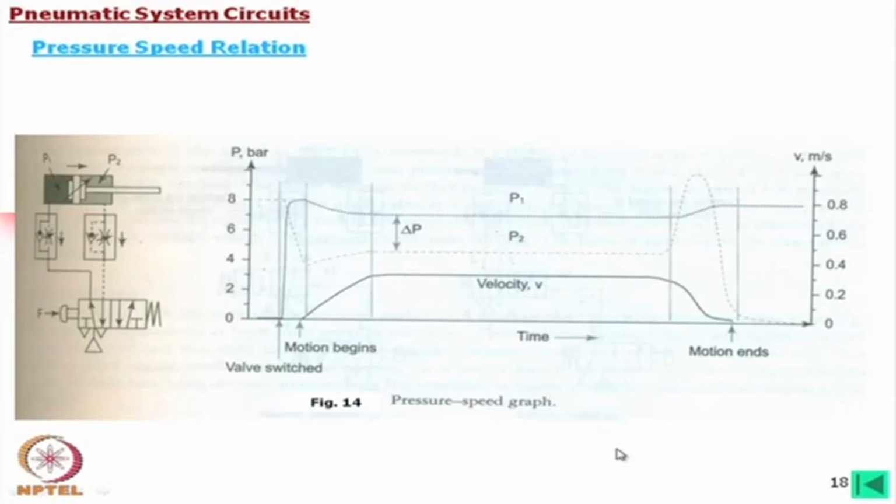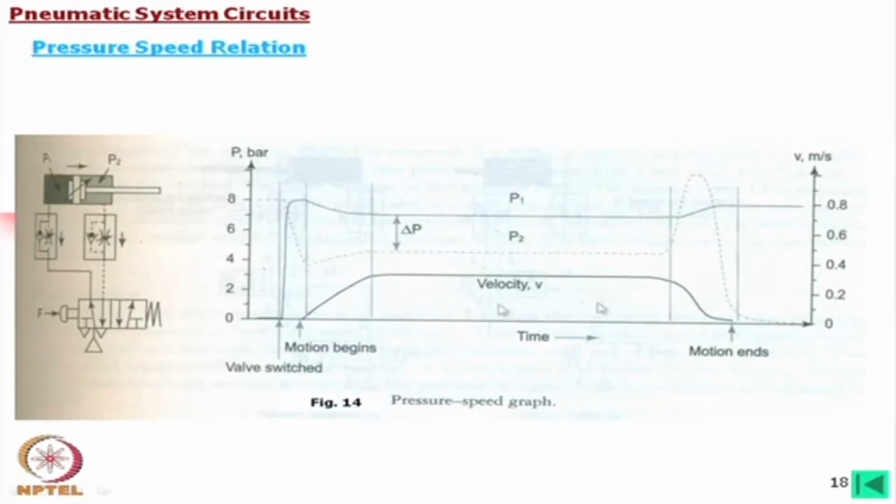Say, for example, we are using this for some cutting operations, such as finishing a plastic, a very soft material, with pneumatics, not hydraulics. In that case, when the tool is moving, we need a constant force, so the operating range must be within this range. Knowing such pressure and speed characteristics is important for such circuits. In case of hydraulics, this zone is very small.